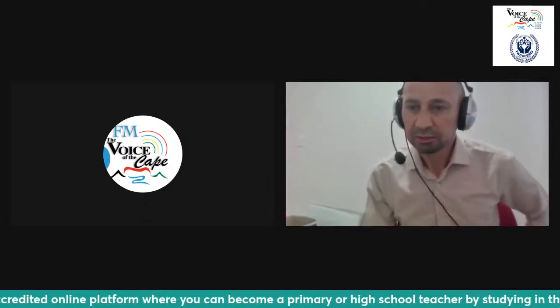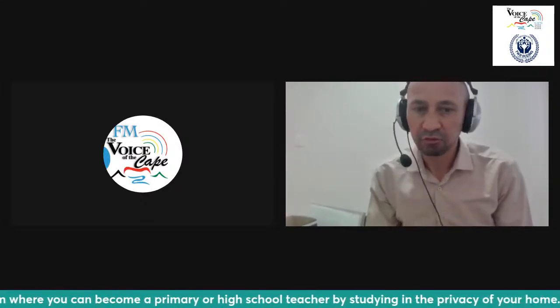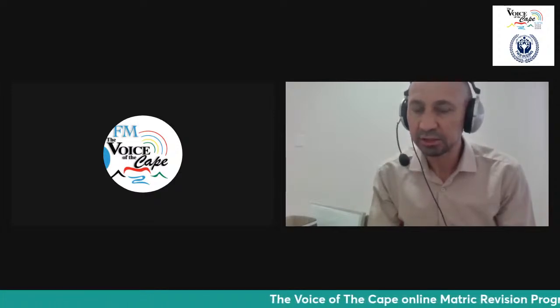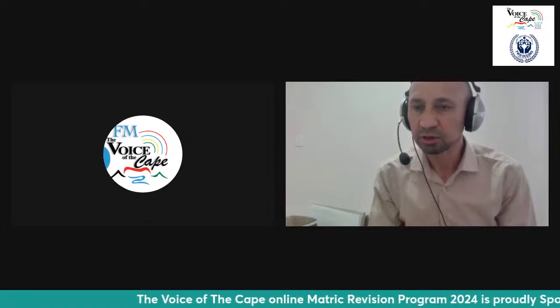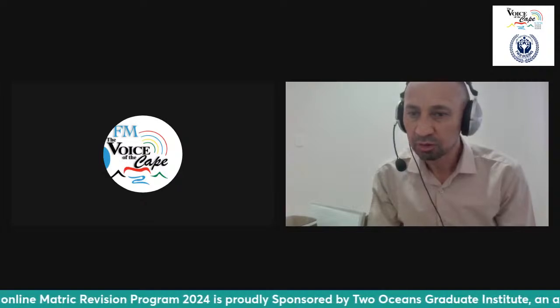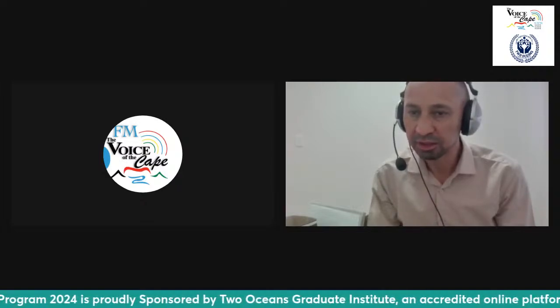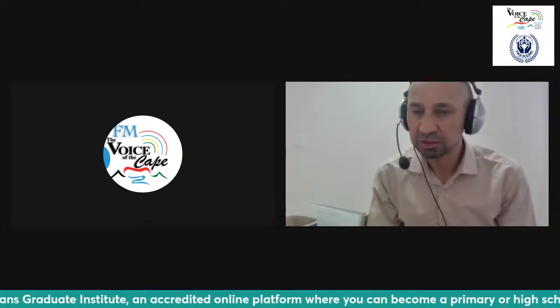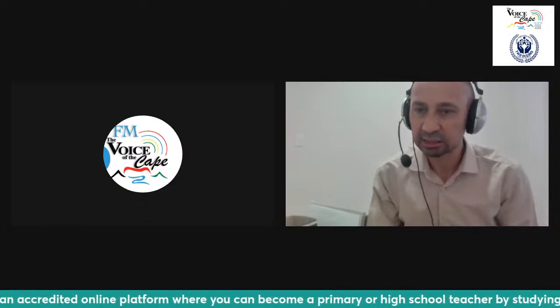So as you can see there, this is basically half a CAM that's been shown, and the CAM follower is now lying horizontal with 0 there and your 360 there. And you're going to find that it has gone halfway as a profile from the designated cam displacement graph. So if you just analyze what we have here, you will see from 0 to 45, which is in between 30 and 60, the cam basically has not moved up or down. So it becomes stationary. So it is at rest, as they call it.